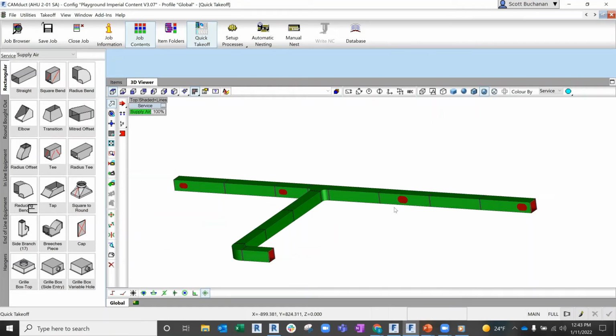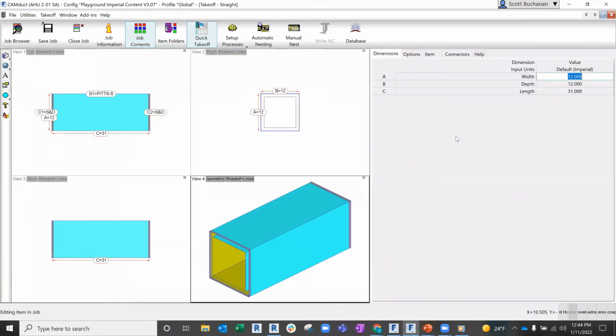So if anybody is on the call that works on the CAM stations or anything, you get the final say so. Just like how I said, the design ductwork gets converted to fabrication parts, has all that metadata. And then when it comes inside of here, you're the last one that's going to work with this before you send it to the table. So if you came into this and you saw there was an issue with something, here's all the properties that are still going to be available to you, right? It's got all that information associated to it.